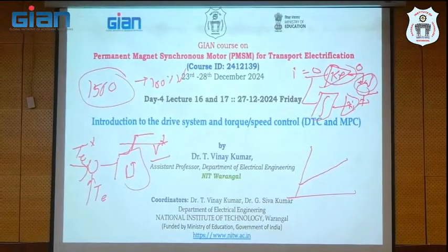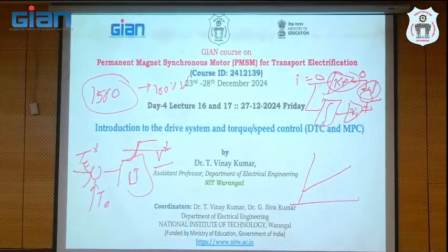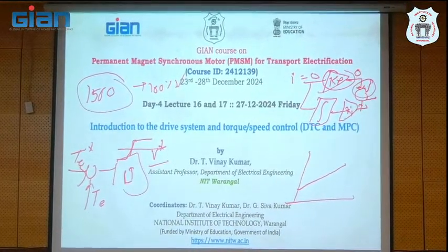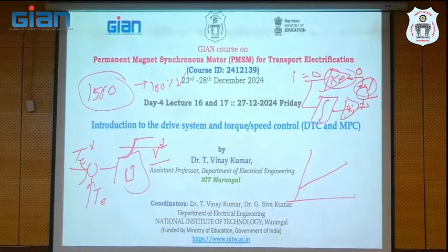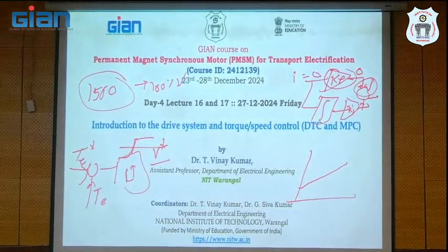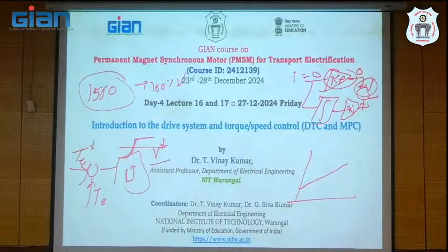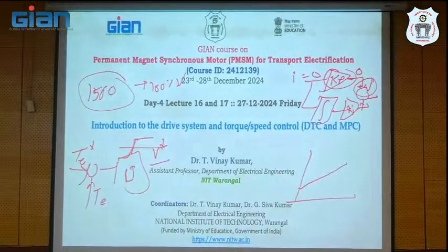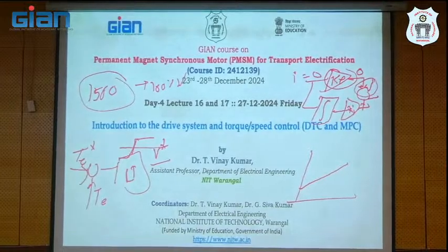You got my point? Now the question is, why, even when the current error is 0, is the Ki output always finite? What is the reason? Cumulative. It will store the previous data, the previous instant, right? Based on the previous instant and the current instant, it will add the data together and produce the required modulating signal to make the error 0, right?